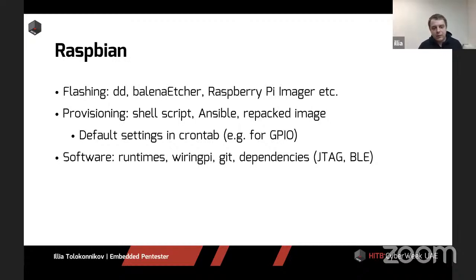A couple of tweaks. We run a lot of default settings in crontab to be applied after the reboot, because sometimes it's simpler to just reboot the whole stand instead of trying to reason why it is hanging or what to do next. So all the default states for GPIO, this will be dictated by how you connect your relay and in what configuration, and everything else like iptables, DHCP settings, anything else that you can think about, put that into the crontab too.